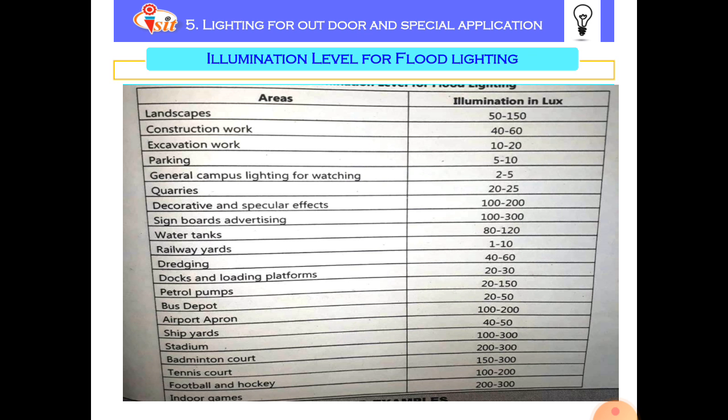Reflecting surfaces are used for the flood lighting. Depending upon the reflecting surfaces, the illuminations illuminate the premises. The material and shape of the reflecting surface of the projector is most important. The reflecting surface is made up of silver glass, chromium plate, stainless steel. For permanent installation, cast metal cases are used to achieve robustness and protection against weather, rain and sunlight. For temporary installation, sheet metal casing is used.